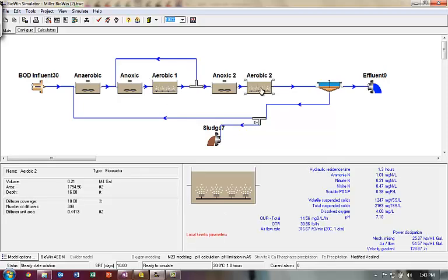And then our second aerobic basin, we again have mechanical mixing at 25.37 horsepower per million gallon, and the airflow for those requirements, how many horsepower would be needed. You've also got these monitored here, oxygen utilization rates, OTR, how many pounds of oxygen per hour, and airflow rate, and how much is being used, standard temperature, pressure.